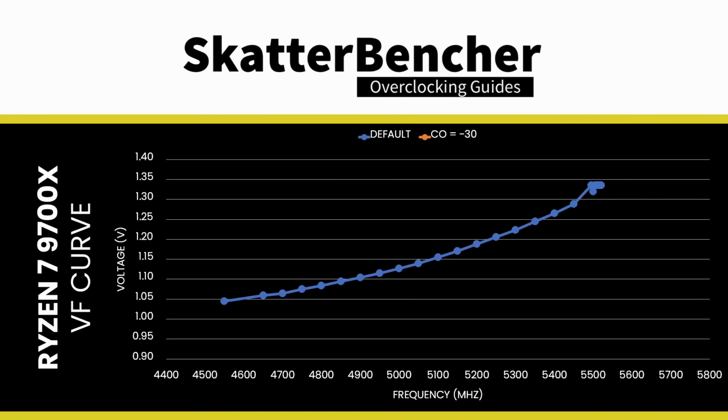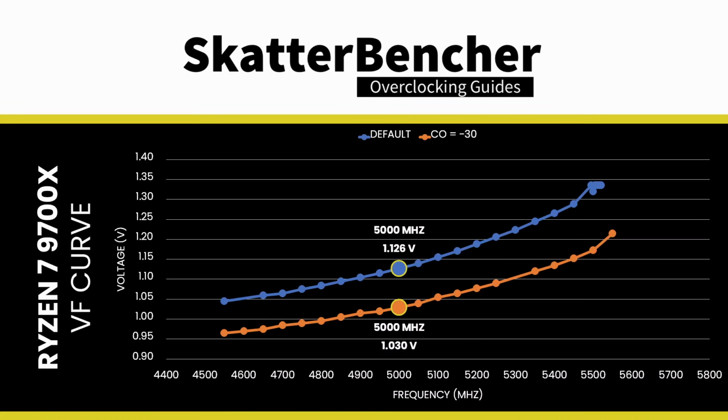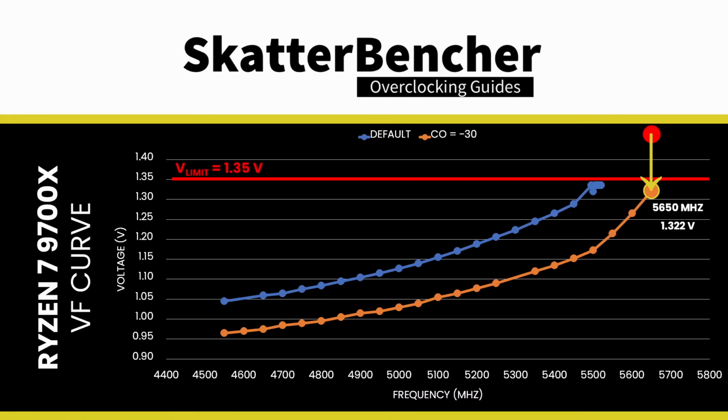If we set a curve optimizer to -30, we can shift the entire voltage frequency curve along the voltage axis. And suddenly, we need a lot less voltage for every operating frequency. For example, for 5 GHz we needed about 1.126 volt by default, but with a -30 curve optimizer, now we only need 1.03 volt. Moreover, the frequency is also boosting higher. The highest frequency with all 8 cores has increased by 180 MHz to almost 5700 MHz. These higher frequencies are now possible because our curve optimizer undervolting pulled them below the 1.35 volt threshold.